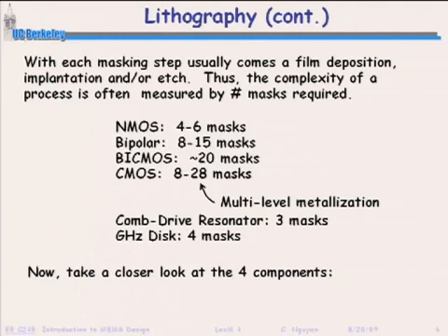So I could say that for my company, for example, we make oscillators, right? It's actually the transistors that cost more than the MEMS. The MEMS are almost 0 cents versus the transistors. So that's where we are with these MEMS processes. And that makes sense, because there are so few masks going into making the MEMS process. The yield of the MEMS is so high that it's almost a no-brainer now. And it's just the transistor and the system that causes yield losses that cause cost increases.